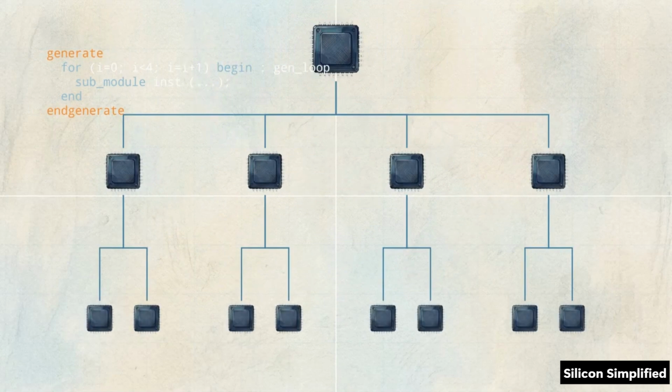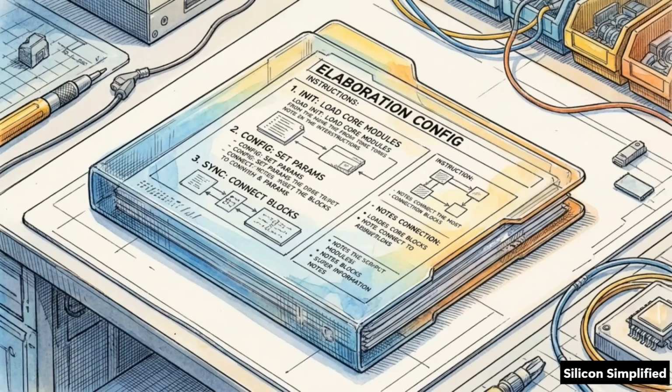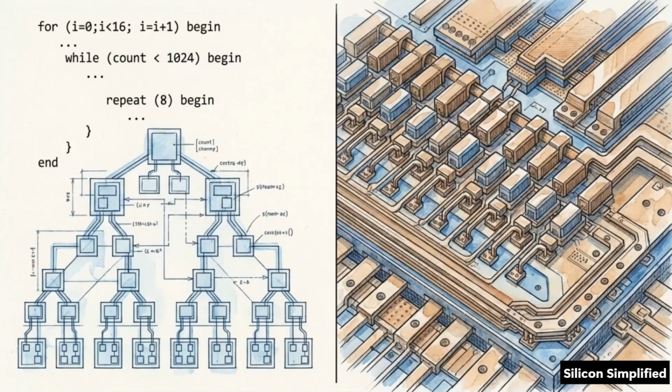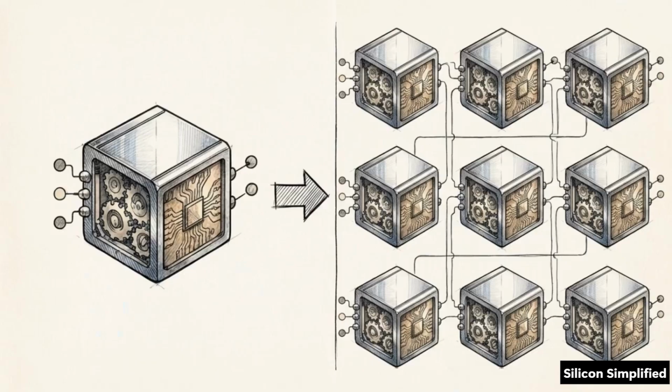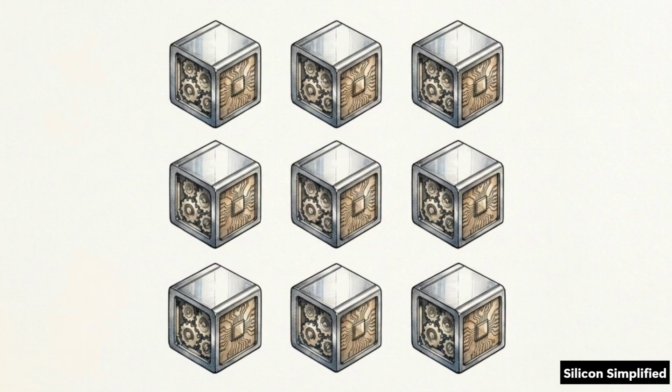The primary application of this tool is the Generate for loop. It replicates repetitive structures without requiring the designer to type out each individual instance. In this Verilog snippet for an n-bit adder, the width of the circuit is controlled by a single parameter. Here, size is set to 4. Below that, the Generate for loop wraps the structural logic. During elaboration, the compiler reads this loop and unrolls the hardware.